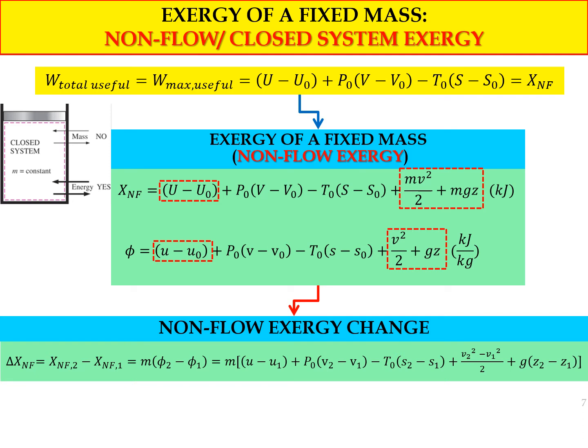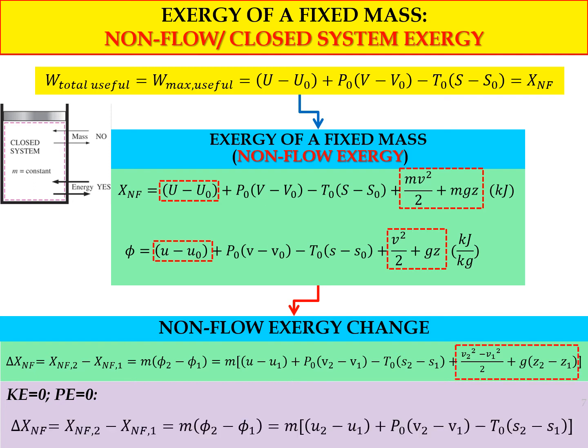And this is the expansion of the equation based on the exergy of a fixed mass equation. And in normal cases, we neglect the kinetic and also potential energy. So the exergy change for the non-flow system will reduce to this equation, as you can see in this slide.